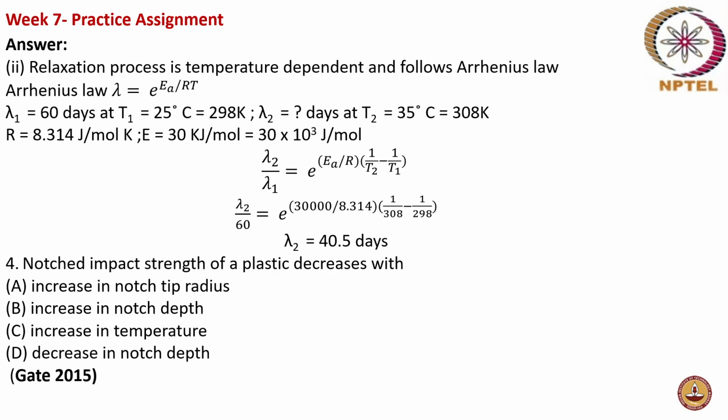Now next, notched impact strength of plastic decreases with: an increase in notch tip radius, an increase in notch depth, an increase in temperature, or a decrease in notch depth? So how does the notched impact strength of plastic decrease? This is again a GATE 2015 question.